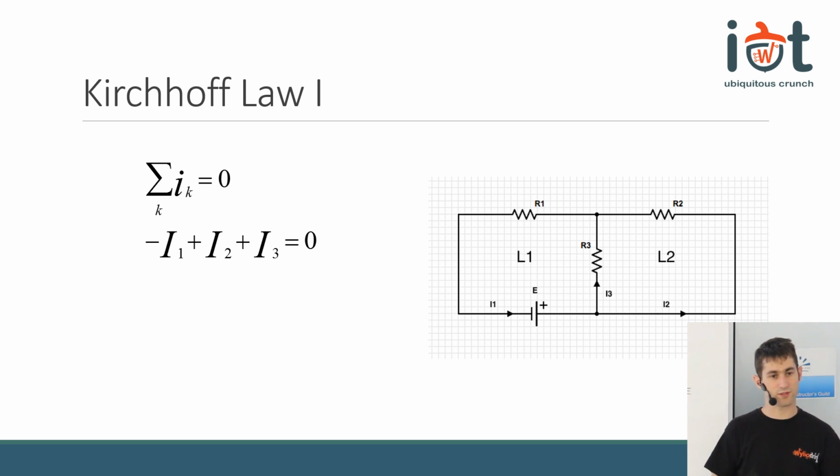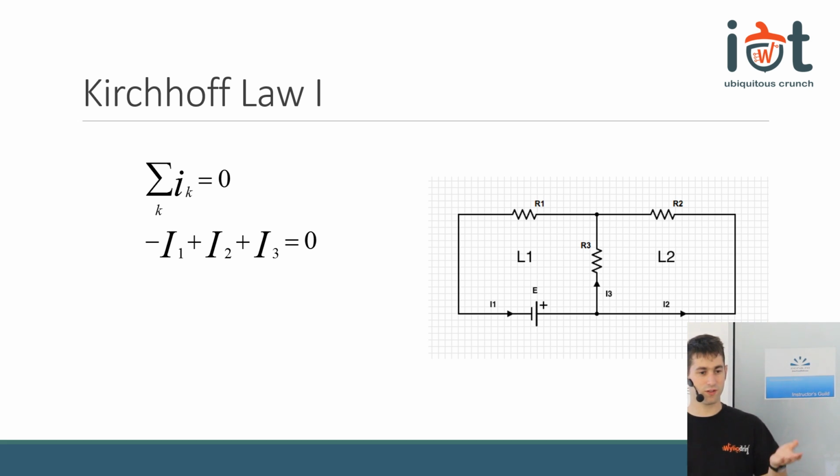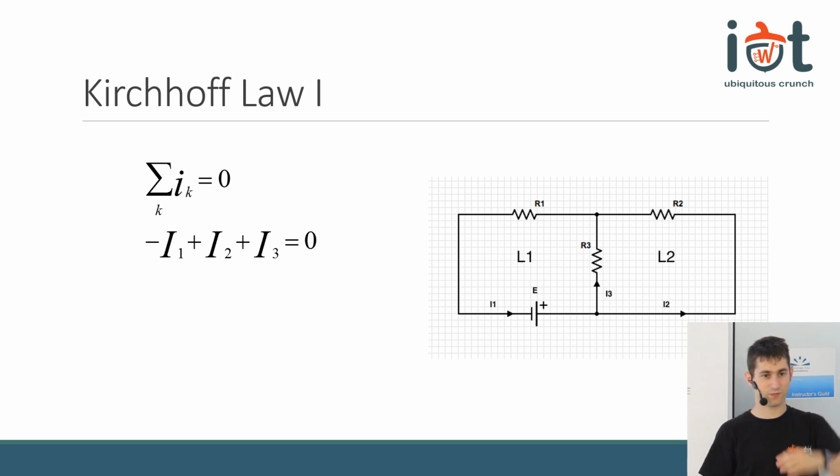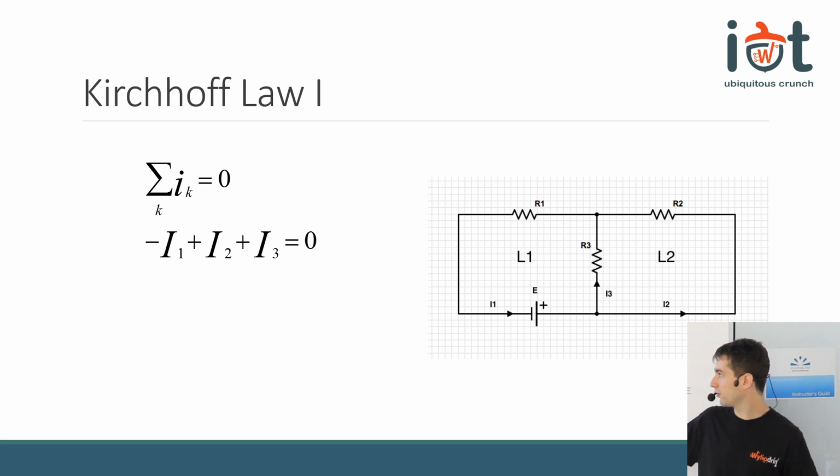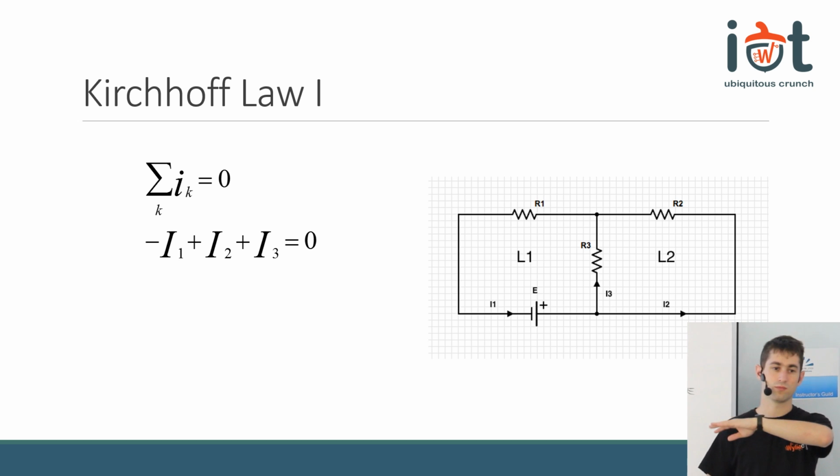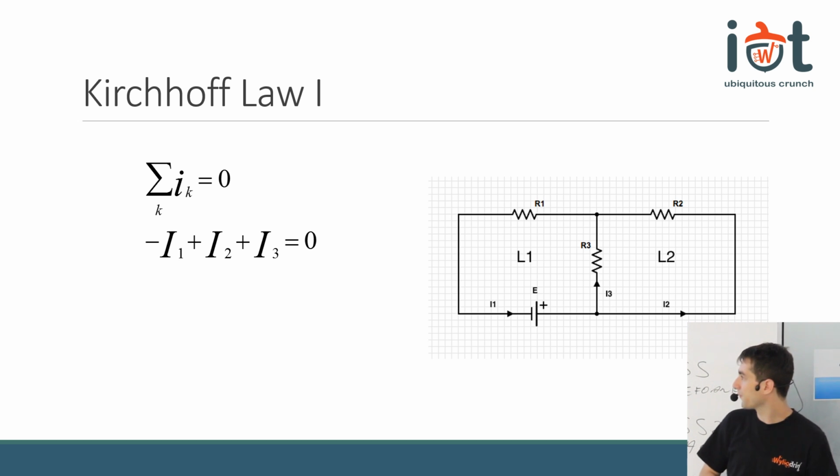It can be written also that the sum of the currents into a node is 0. And currents can be positive if the direction is outside the node, and negative if the direction is inside the node. Usually the sign of the current doesn't matter, the direction of the current doesn't matter, you can choose it however you like. As you see in my picture, I chose the currents to the right. If you put the current vice versa, you simply might get a negative value. So if you get a negative value for the current, the flowing direction is actually in the opposite sense. Is this clear?